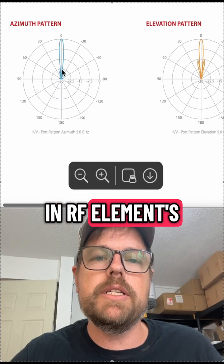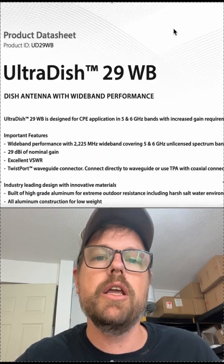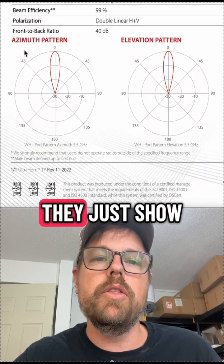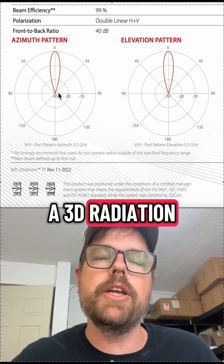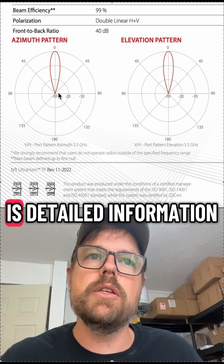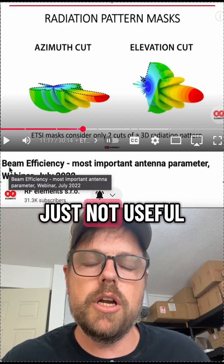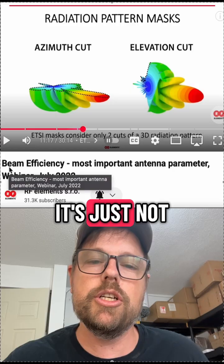In RF Elements datasheets, they also just show you the azimuth cut and the elevation cut. This is the Ultra Dish 29. That's also true for the Ultra Horn. They just show the azimuth pattern and the elevation pattern. A 3D radiation pattern isn't necessarily useful. What you need is detailed information to use. And the basic problem with beam efficiency is it's just not useful. You can't do anything with it. It's not that it's incomplete, it's just not useful.